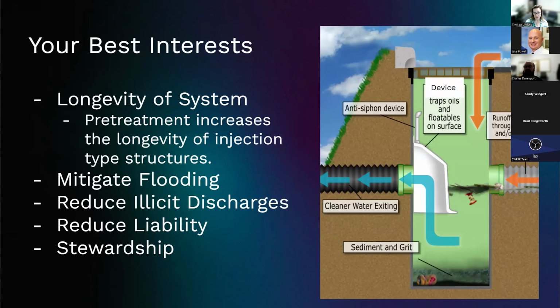So this device you see, it can be like a 90-degree elbow, or it can be something that's, I don't want to say proprietary device, but a snout. How it functions is all the sediment can settle down as that water sits there. It's ponding. The sediment settles out.